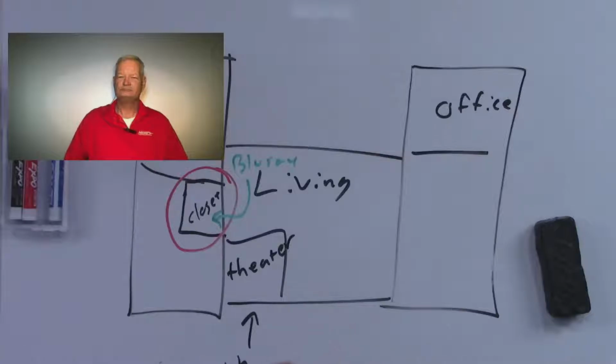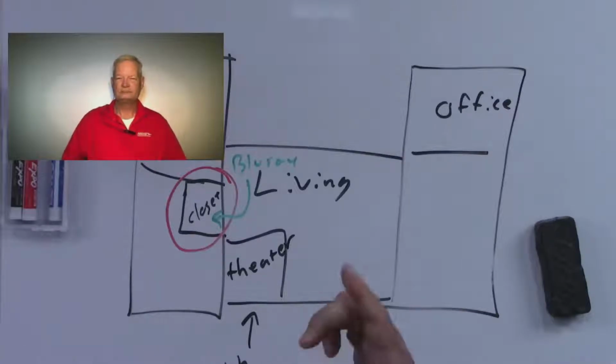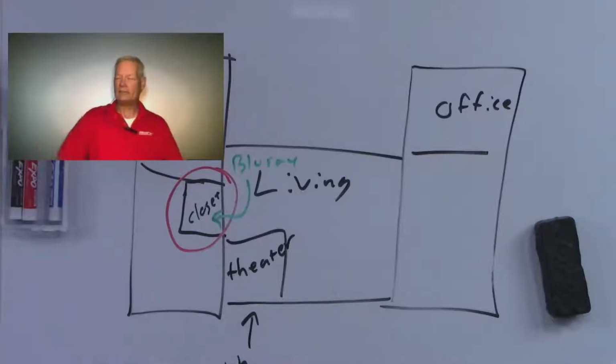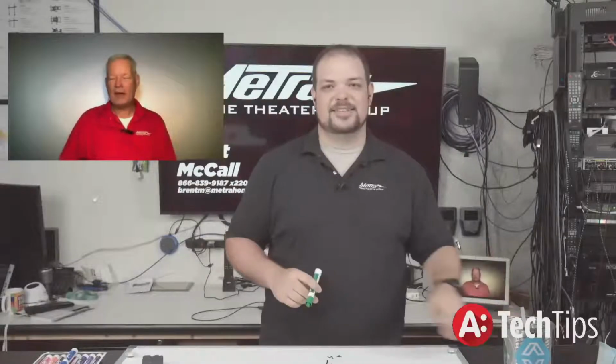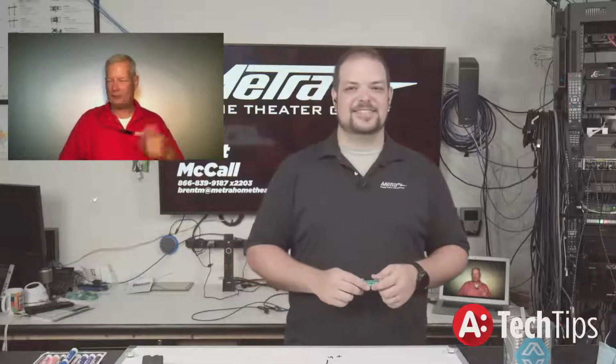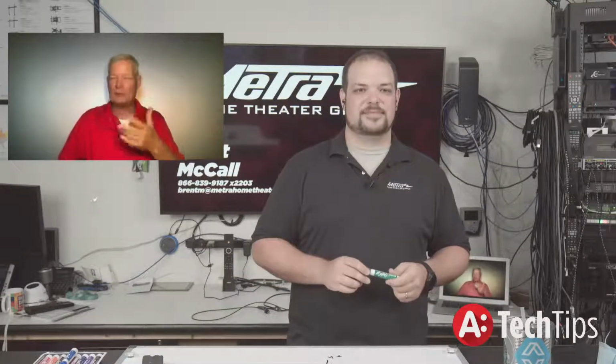Run extra wires. Now, Brent, do you remember how many he ran in his installation? Yes. He ran three Cat 6s and a coax to every location. And why do we like that so much? Because you can never have too many pieces of wire, because Cat 6 can carry video, or audio through our Balun, which we had two weeks ago.